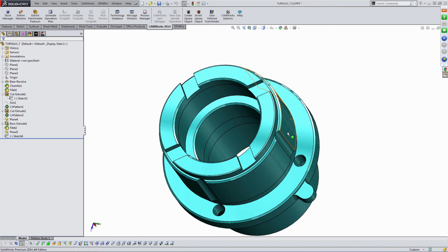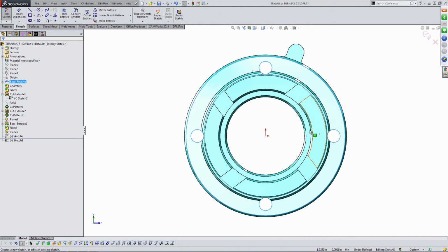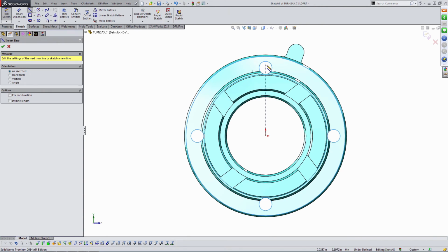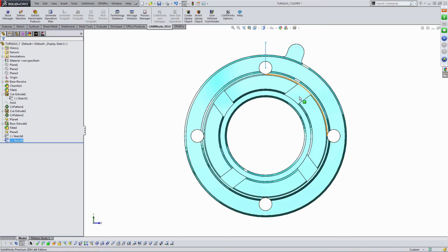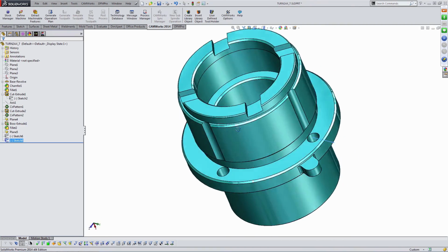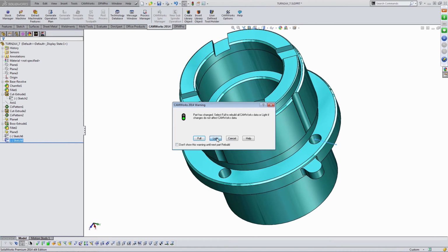To kiss it, I'm going to have to follow a line. So I'm going to start a sketch on this face, and I'm going to use this existing edge here. Just something like this. I'm going to run my tool right along the center of that using something called a curve feature. So this is a 2.5 axis feature.